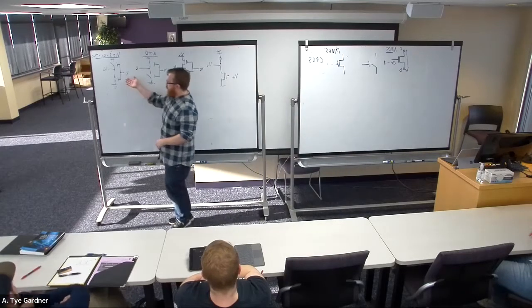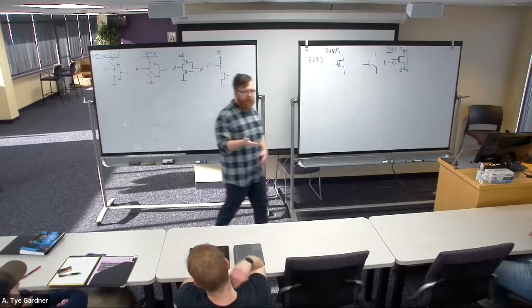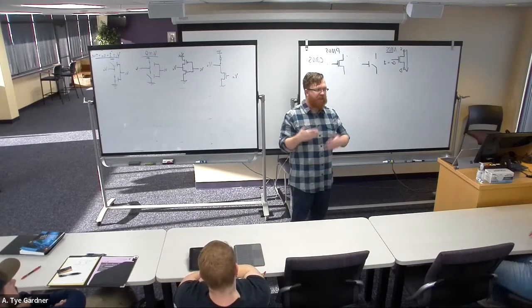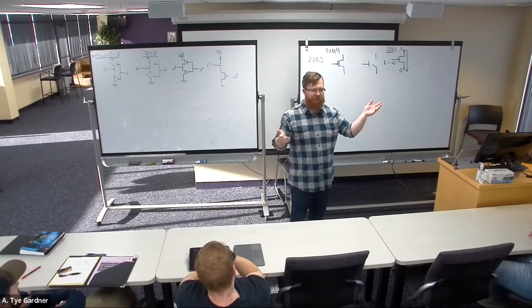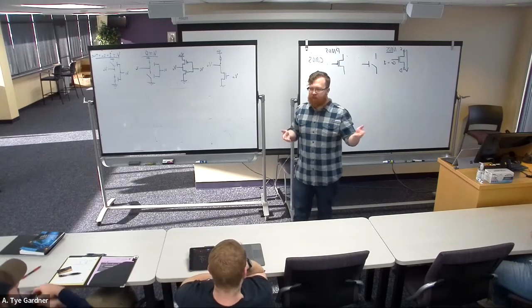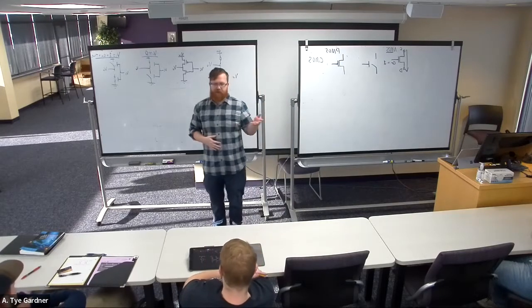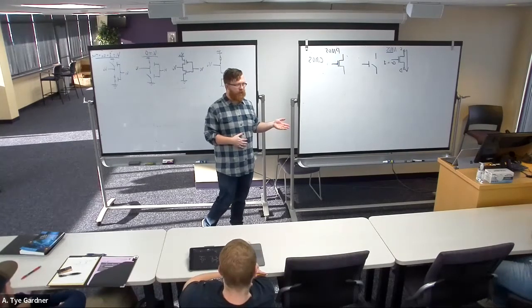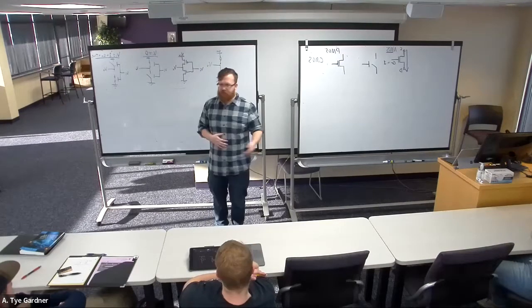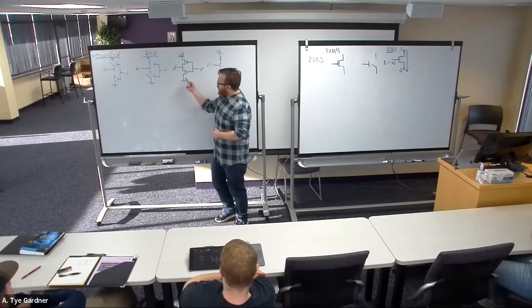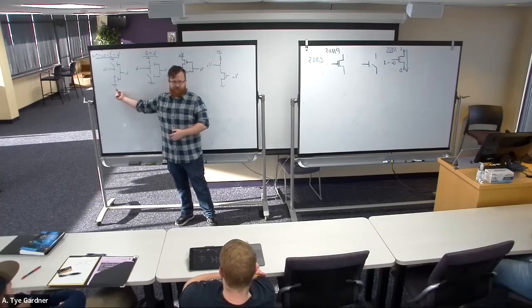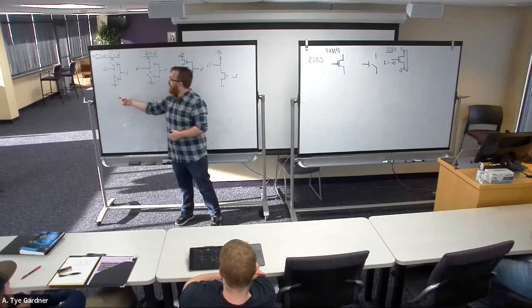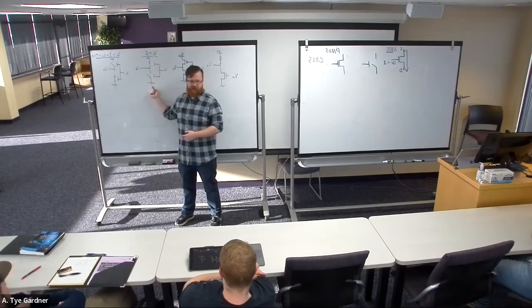Something that's cool that's happened here is devices, right? Remember I talked about the NAND gates and how in an ideal world there would be no input current, but there's a little bit of leakage. Well, the devices that you have actually have really bad leakage current. Most of the time it's very small, and we pretend like no current flows through the gate. And also, when we look at this device, if in either of the cases one of the switches is open, there is no path between VCC and ground ever. So there's no power consumed.